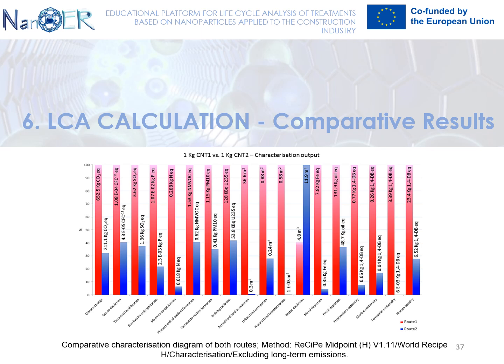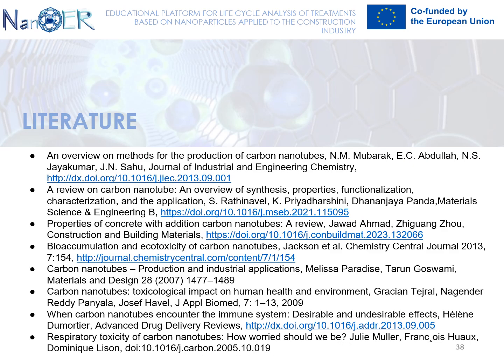Secondly, the higher productivity of Route 2, the supported catalyst approach, results in a drop of the environmental load, which implies that more Route 1 batches are necessary to achieve same production volume. So the heating stage is the most impactful part of CNT life cycle and thus a focal point when considering the process upscaling. Apart from energy, the use of silicon substrate, which is essential for the orientation of the final material, is another contributor to the Route 1 environmental print.